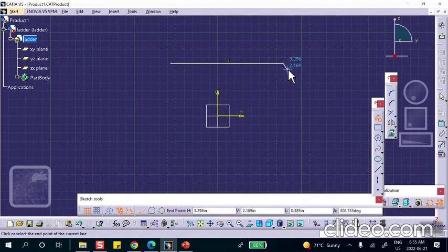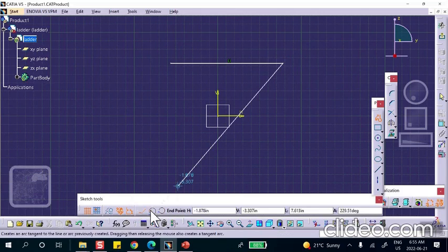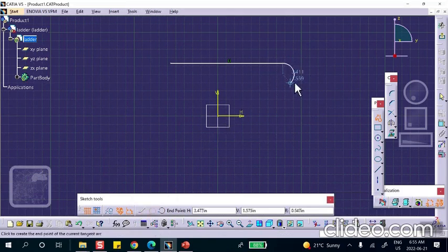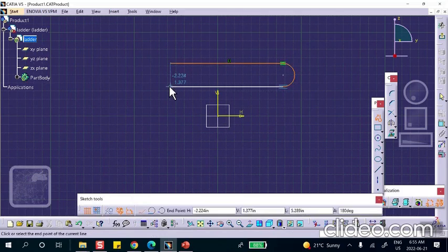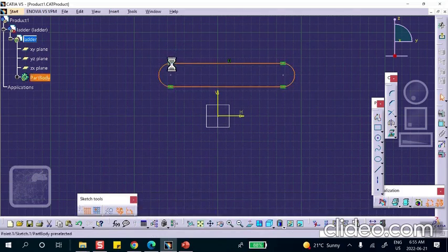Now notice that I was going to make a circle here, and I missed the opportunity. Left click, hold down, and drag a little bit. But that's okay. You can always go to here to sketch tool and clean it up right there. See that? We come down here, and then left mouse button down, drag it a little bit, and it turns into a circle. Otherwise, you do it with what I just showed you.